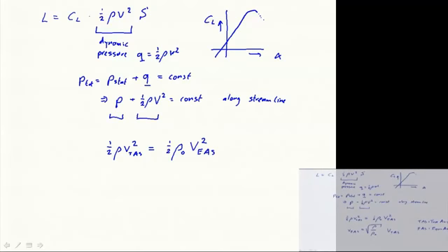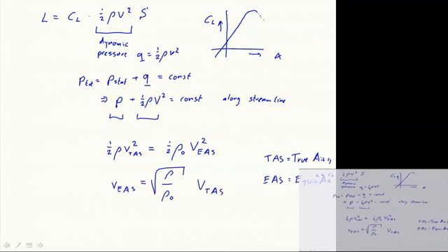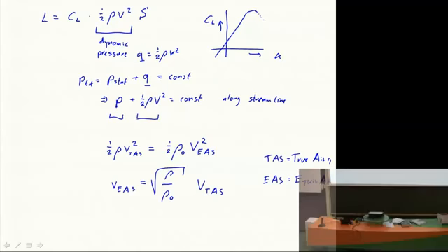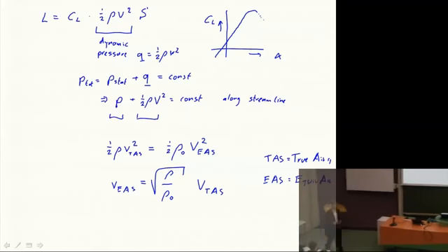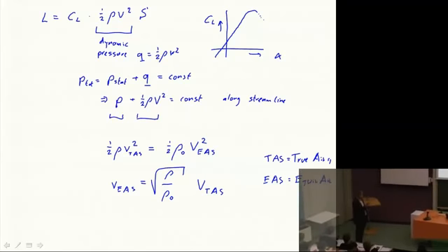It doesn't really matter that your real airspeed is 200 knots. If the aircraft has a stalling speed of 150 knots, it will stall anyway, because that stall speed was calibrated at sea level. So all your red zones on the speed indicator are calibrated at sea level, and this is why the instruments inside an airplane indicate the indicated airspeed, which is very close to the equivalent airspeed. There are only some instrument effects between them, but we'll leave that out for now.